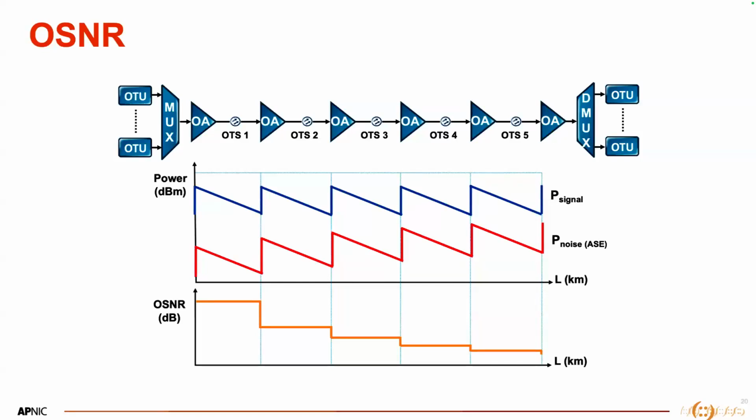Say suppose the optical power of a signal is minus 2 dBm or minus 3 dBm, right? And the noise you are having in that signal may be minus 2 dBm. So your OSNR should be straightforward, 3 divided by 2. Whatever the result is, that's the OSNR for that lambda in your network. So you need to find out what the noise level is and what the power strength of the signal is, and do the manual calculation.